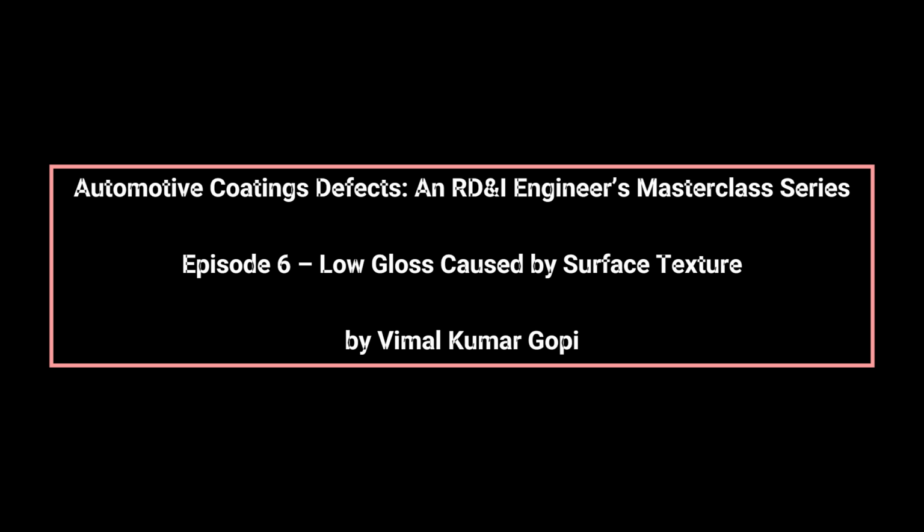Additives have a supporting role, but never a corrective role when texture is the dominant factor. Flow agents, surface tension modifiers, and rheology modifiers can optimize surface formation only within a properly controlled process window. When that window is exceeded, additives become ineffective or even counterproductive. OEM RD&I teams therefore treat additives as fine-tuning tools, not defect cures.